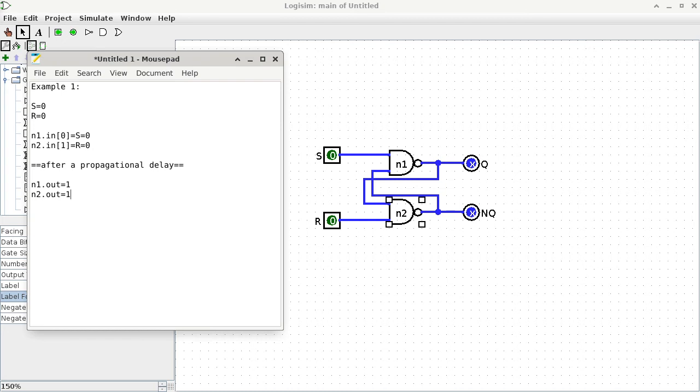One way to look at this is a truth table. Okay, so I'm just going to show this once so that you guys can hopefully remember that. So this is X NAND Y. When X and Y are both zeros, X NAND Y is a 1. If X is a 0, Y is a 1, the output is also a 1. That is also a 1. The only time the output of a NAND gate is a 0 is when both inputs are 1s.